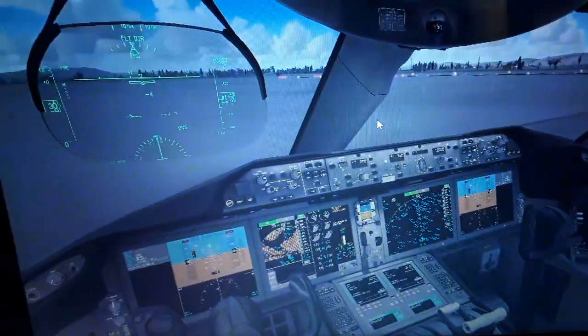It displays the airspeed indicator, the airspeed selected from the autopilot flight director system panel, the ground speed, the radio altitude above ground level, the barometric altitude above sea level, the barometric pressure of the outside atmosphere, and the target altitude selected from the autopilot flight director system panel. The vertical rate of climb and descent of the aircraft is shown in feet per minute.